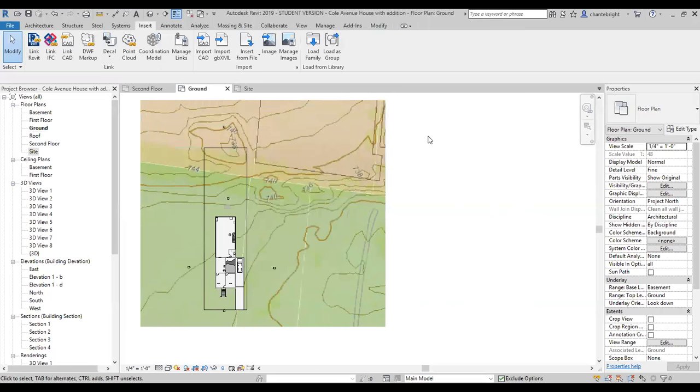So here's the next thing that you want to do. If you did not take the time to set up sea level, which is something you have to set up inside of Revit, and make sure your survey points are correct, but we haven't done any of that. We're doing this the quick way. So just keep in mind, you want to decide what's going to be 0, and you have to make that distinction now.